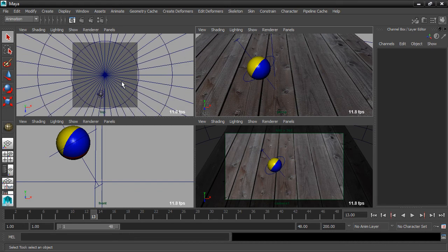And we want to create at least 2 lights, really, in any situation. We want to have a key light, which is going to be the dominant source of illumination, and a fill light, which is the ambience or the bounce light. If this is an outdoor scene, then we can use a directional light for the sun and an ambient light for the sky or the environment.